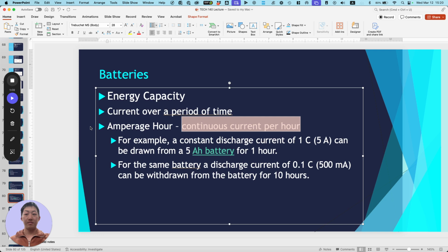Okay, if you look here, this is the top. This is the top because it has the power plug coming up. So there's one end of the plug. One of your spacers is thinner. You see, this one's thinner, and then the one that goes on your IMU or flight control board is thicker, and it's not evenly thick. One side is going to be thicker, and the other side is going to be much thinner.